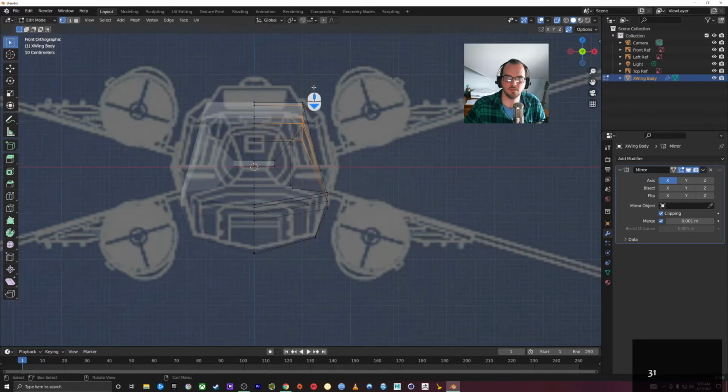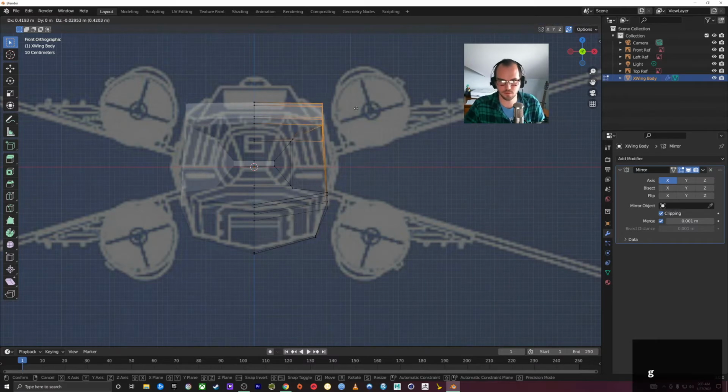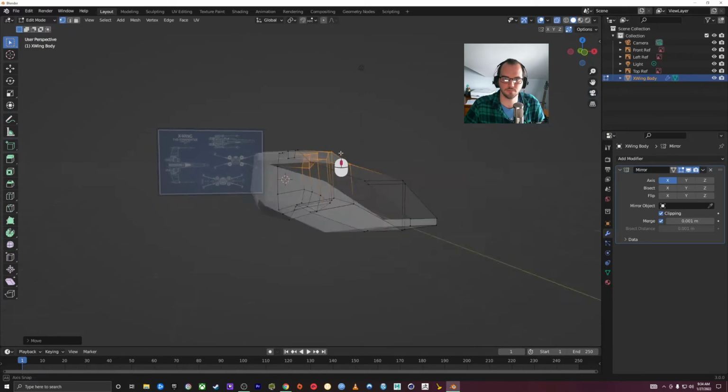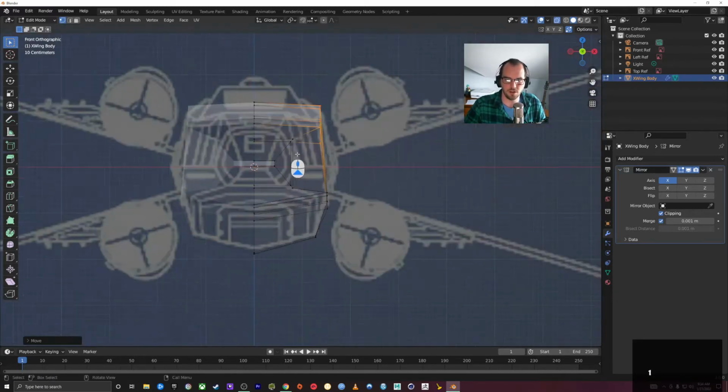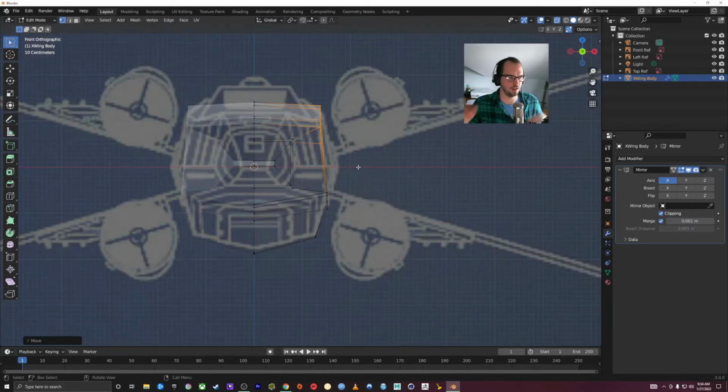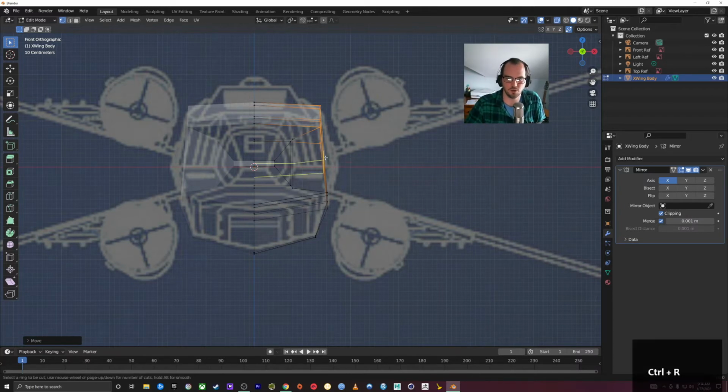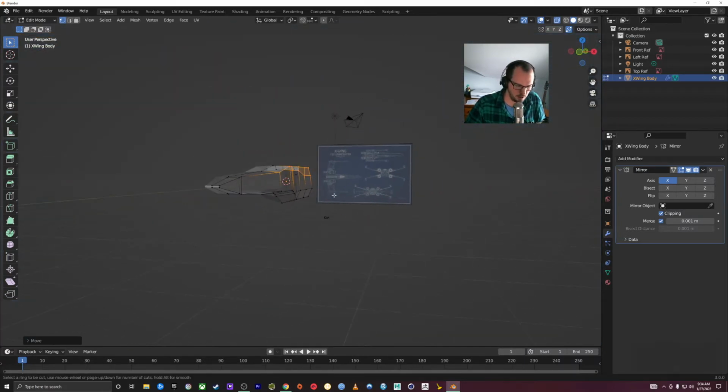These ones are like the back, kind of like this, maybe. The front ones I'm not going to change too much because I think the front was fine. The other thing I'm going to do here is, because I want that little outward thing, I'm going to add a loop cut all the way around the center. So I'm going to Control R, and you can see, let me get out of that. If I do Control R again, it tries to find the middle of the thing.